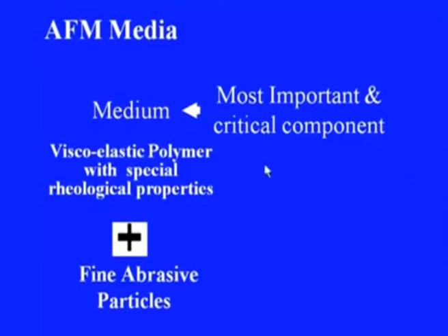Here is the method of how a media is prepared. First of all, as I said, a viscoelastic polymer is taken with special rheological properties, that is viscosity, and then added to it are the fine abrasive particles. Of course, their fineness is to be decided as per the requirements. For getting a very high surface finish we have to use fine abrasive particles, and so on.